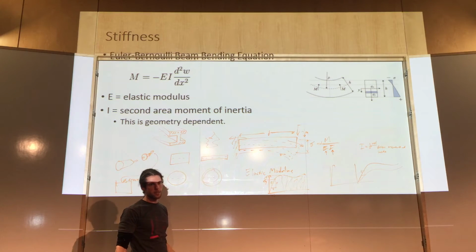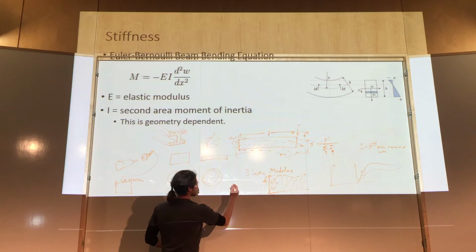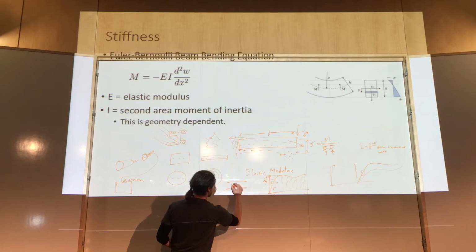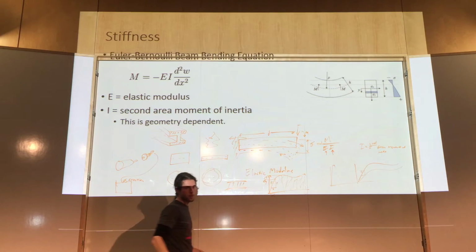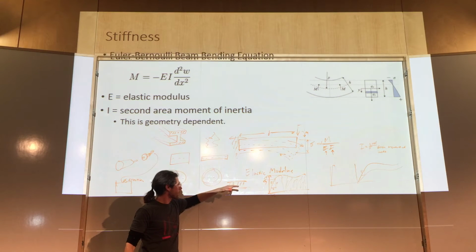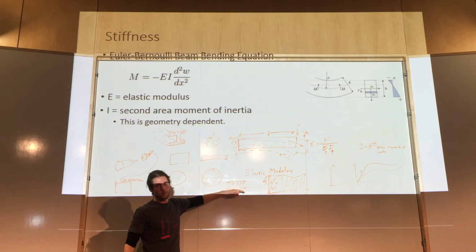And that's why composites, like in high performance airplanes or cars, have the foam core with carbon fiber. You've got carbon fiber, and this foam core in between them. The whole point of that is to put the fibers that are taking a load where they matter.